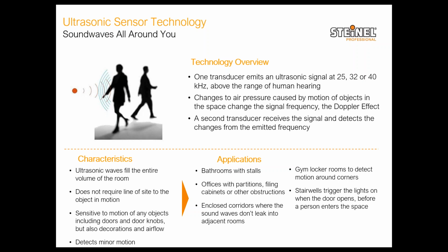Then you have another transducer that is listening, and once it receives the sound wave back and detects that there is a change in the frequency, it will consider that as a movement. This makes ultrasonic a very accurate, very sensitive technology, but it will have its own drawbacks because of this.